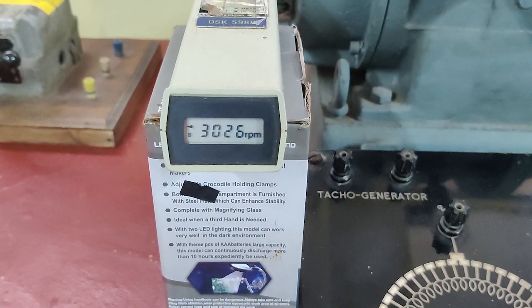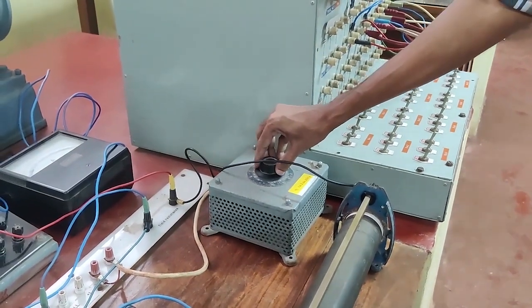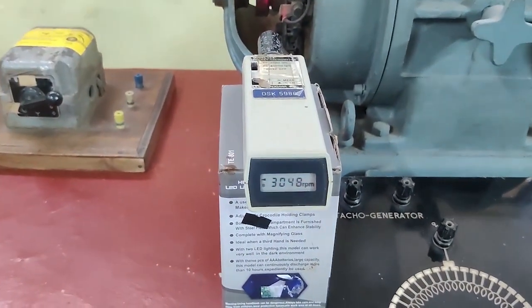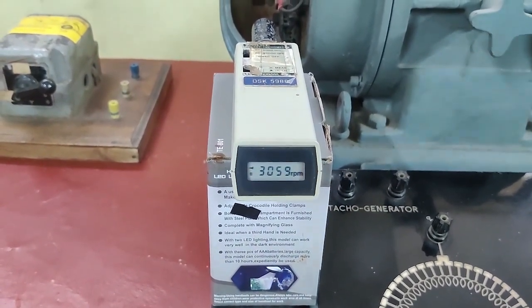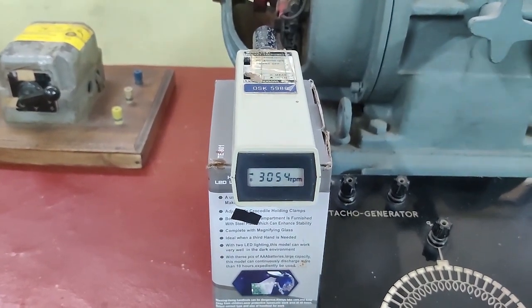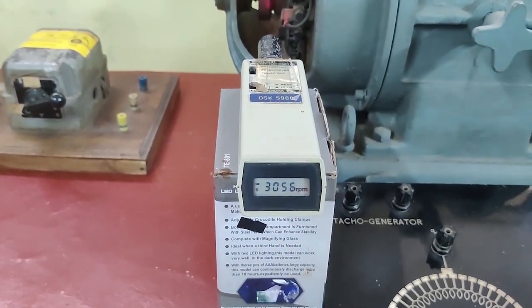Similarly, we have to take the line current, voltage, frequency, power and torque readings under this condition. Please note that this part is not shown in the video. Here, the ammeter reading corresponds to the excitation current drawn by the induction generator. Now we have to increase the speed in steps of about 25 rpm. We can do this using the field current control. And then we have to take all the above readings once again.